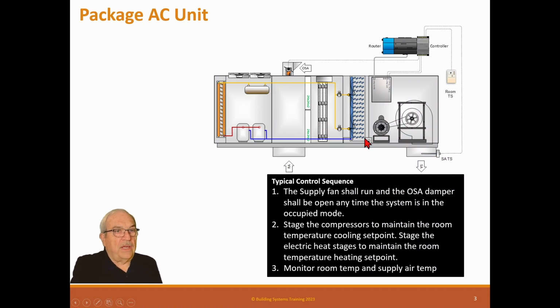And the reason for that is compressors don't like variable flow air over their evaporator coil. The reason is because this gas coming back needs to be vapor. It can't have any liquid in it. It has lots of thousand little droplets of refrigerant that have heat in them, but they're not coalesced together to actually provide a liquid.